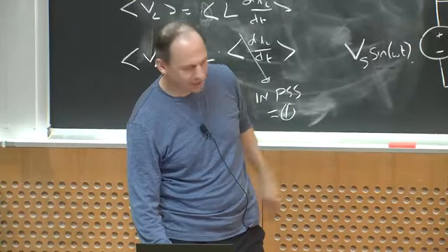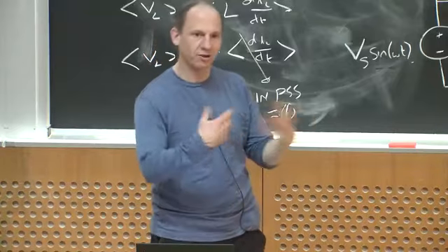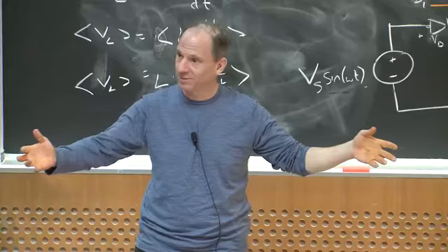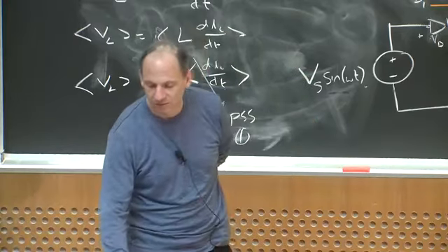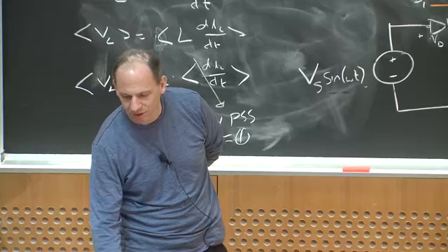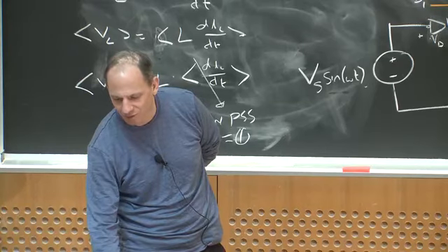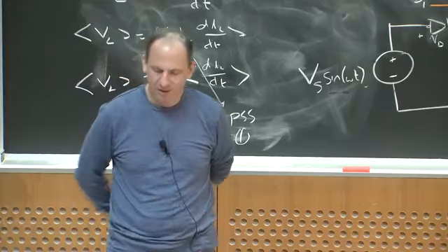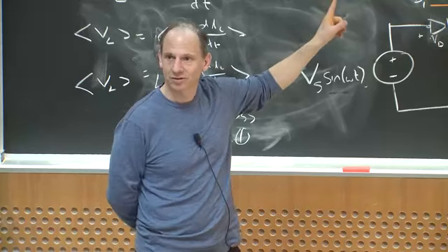So anything I might say about steady state operation is not true down here right after I've started this circuit up and it's coming up, right? Real circuits have dynamics. It's doing something dynamic. But the interesting thing is, eventually I get way over here and look at this. If I zoom in on this right-hand portion of the circuit after I've waited for a while, everything's repeating every cycle. That's periodic steady state operation.